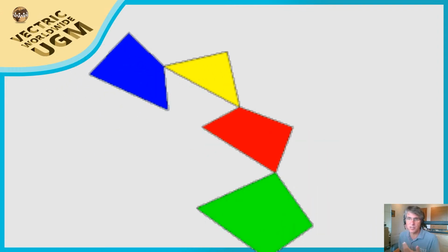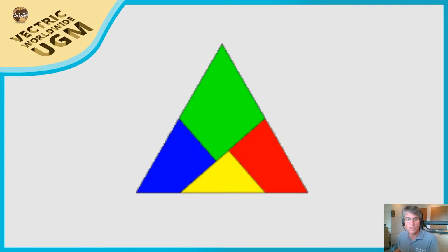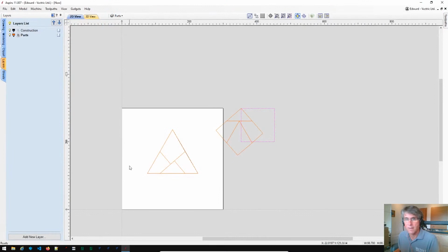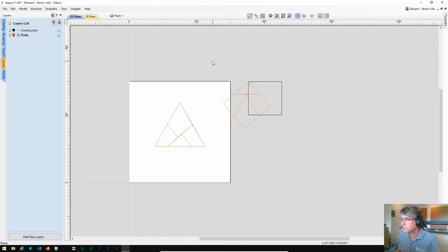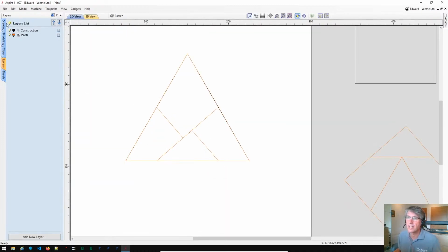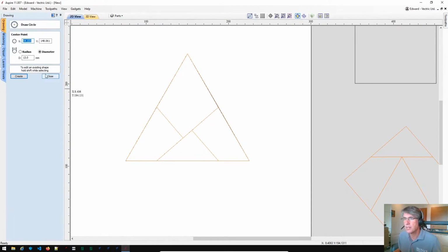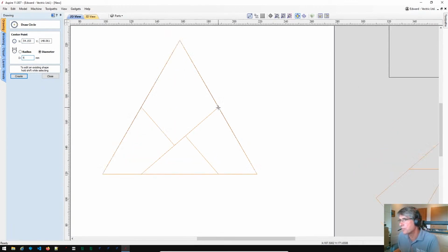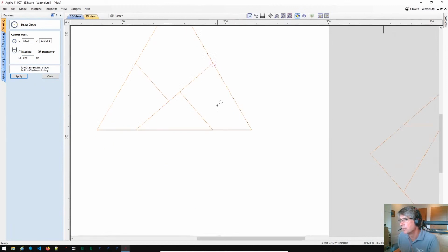And the way I'm going to do that is going to basically drop in some hinges. So we'll go back to my design here. Let's drop those out of the way for now. So where were the hinges again? Let's pop those in, and we're going to make them, let's just do some little 6 mil. I need them to be pivot points that are going to be strong enough in the wood. I've chosen 6 mil just to be a reasonable kind of size. So there's going to be a pivot point there, a pivot point here, and a pivot point here. Not one here actually, because that's the split if you imagine.